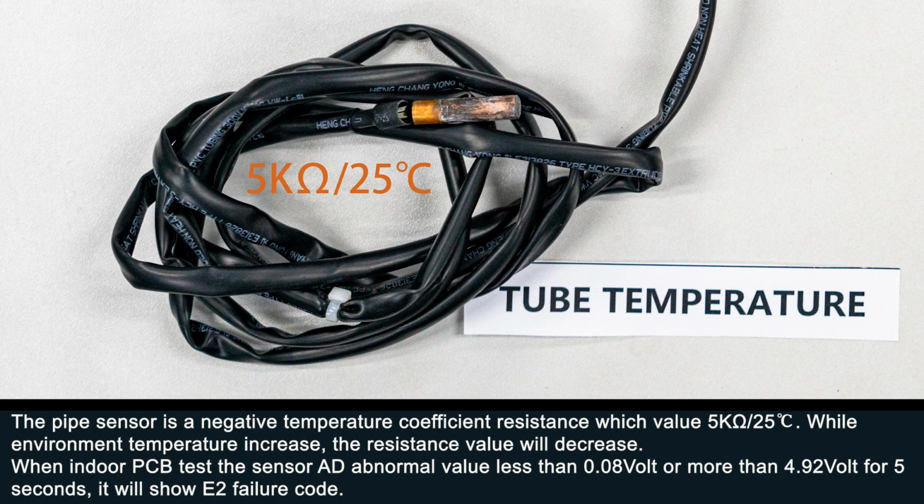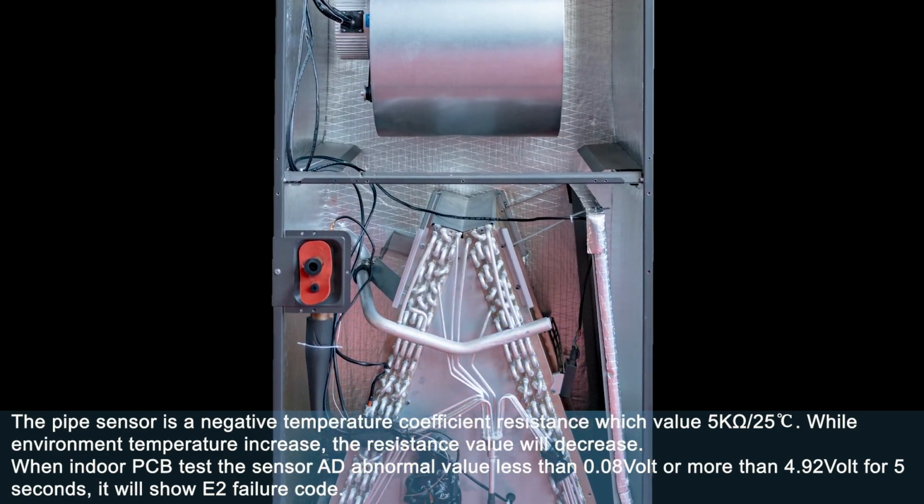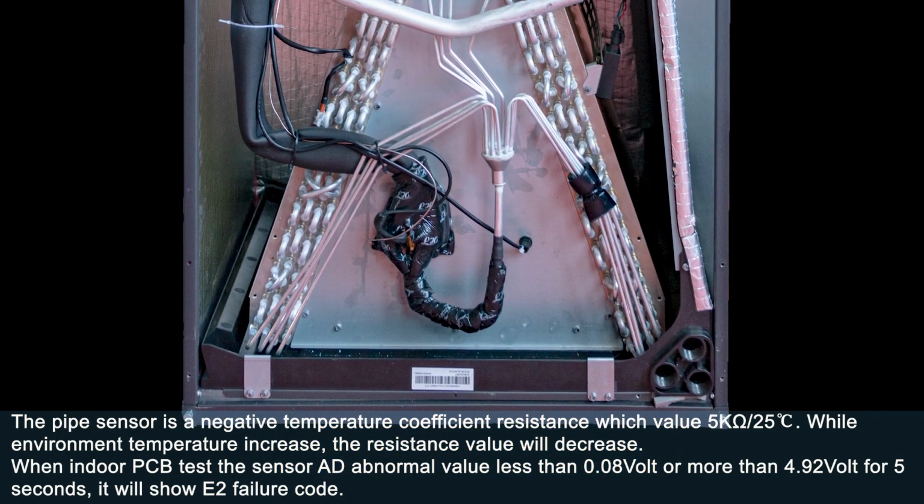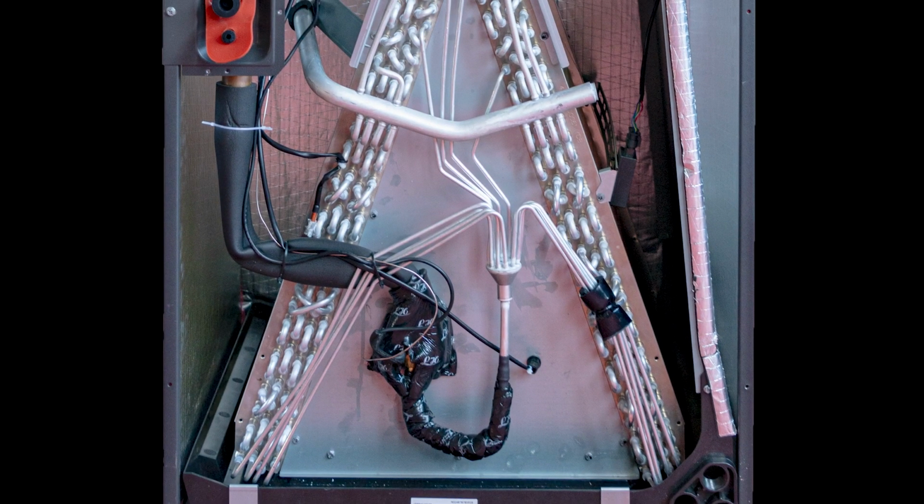E2 means the indoor unit evaporator pipe temperature test failed. The pipe sensor is a negative temperature coefficient resistance, with a value of 5 k ohms at 25 degrees Celsius. While the environment temperature increases, the resistance value will decrease. When the indoor PCB tests the sensor AD abnormal value less than 0.08 volt or more than 4.92 volt for 5 seconds, it will show the E2 failure code.